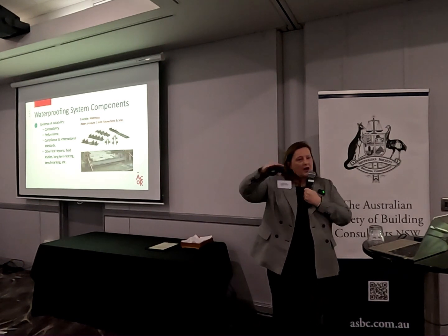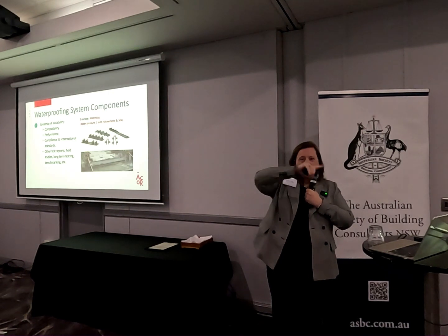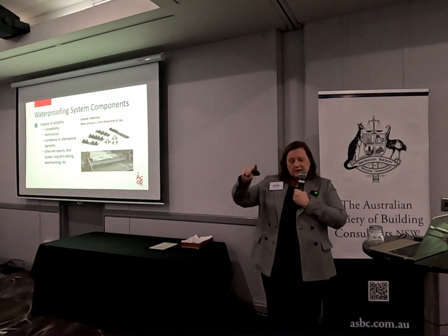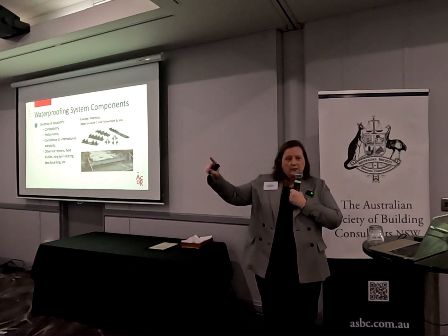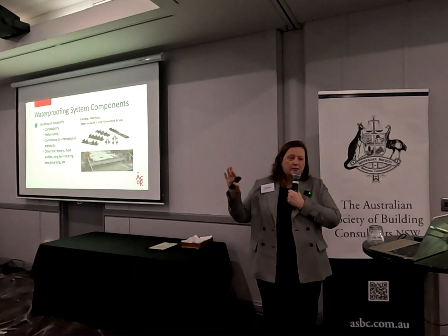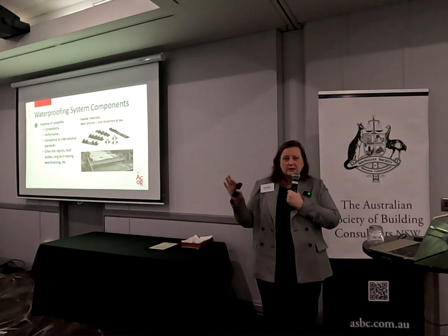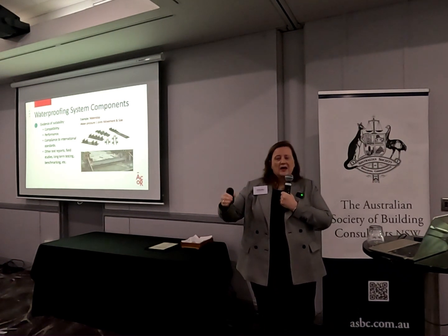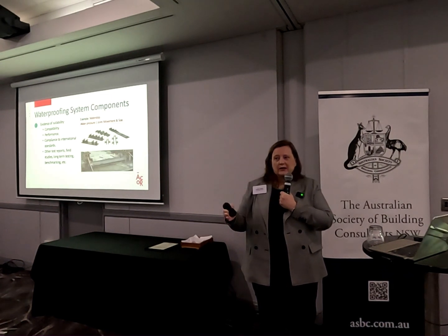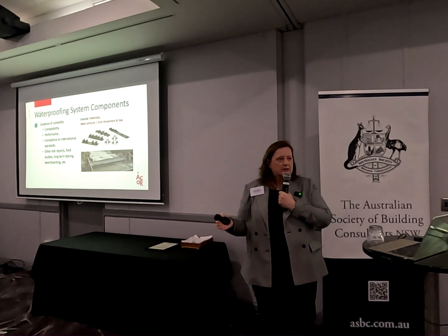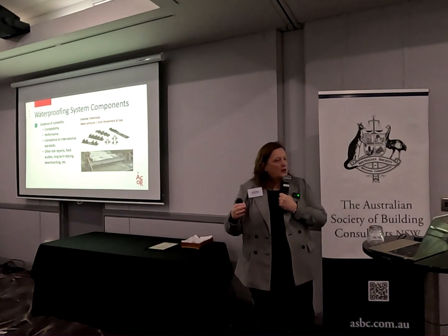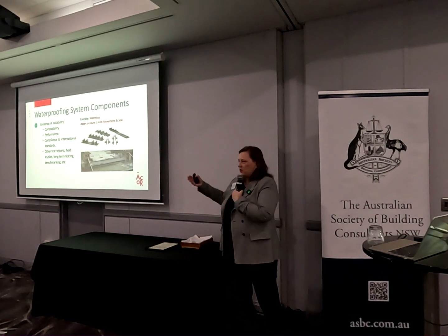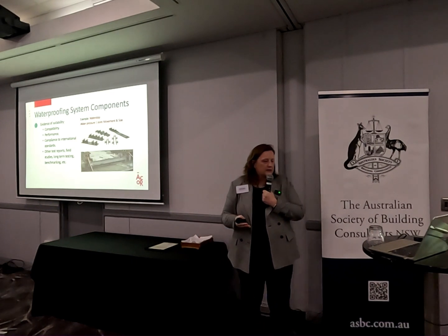You can imagine if it was flat, that's not as tortuous as something that has high ribs or many ribs. I often see on drawings, it'll just say PVC water stop. But within that, there can be a lot of different profiles, a lot of different performances, and where it's critical, I really do think that sometimes we need to go that extra step of saying exactly what is needed, or at least putting some kind of performance or other requirement in there. That's why I started the presentation talking about components, not just membranes. I want to have a more holistic view of what goes into a successful outcome.